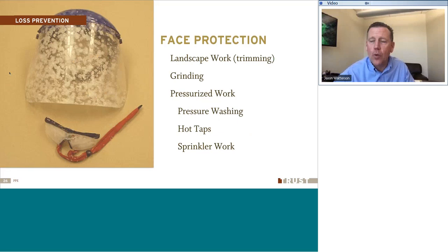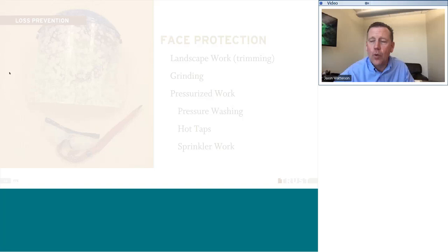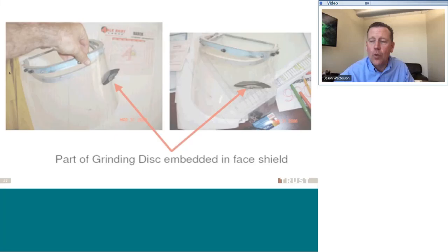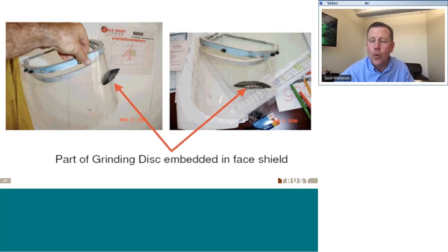All right, next section, head protection. We talked about this already. Anytime I'm working where there are elevated loads, things that are being hoisted above my head with cranes, with excavators, anytime I'm working in excavations. So if I'm in a trench, I need to have a hard hat on. That's just the rule. And anywhere where there's potential for falling objects or being struck in the head, I need some type of head protection.